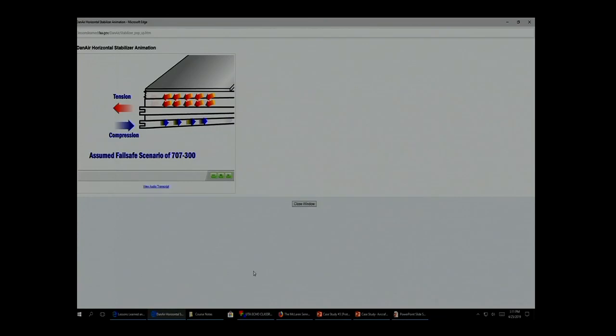So they tested this for the Boeing 707-100 with two cords, and then they added the center one, thinking that the center one will take the load if the top one breaks. But they only did analysis, they didn't do test. The stabilizers of the 707-300 and 707-100 were similar enough to use the 707-100 test results to validate the assumptions made by the manufacturer.